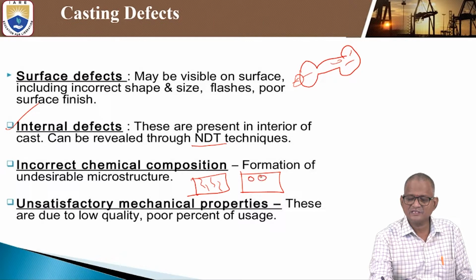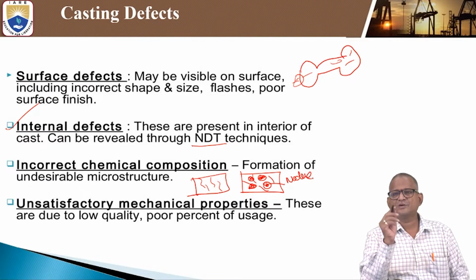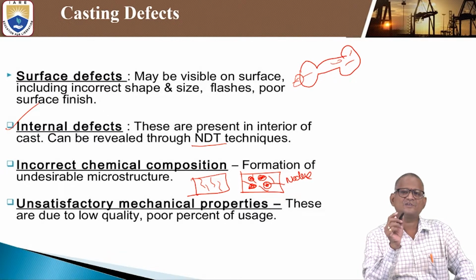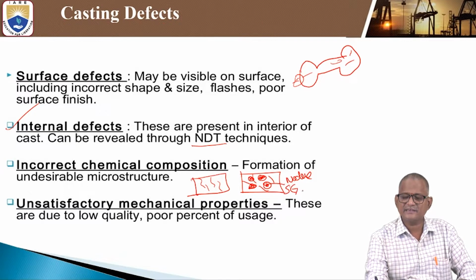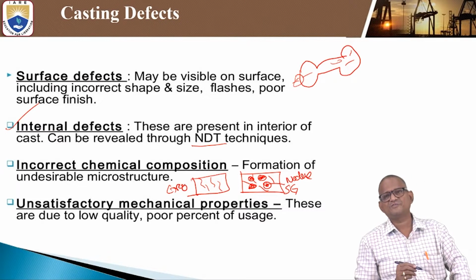In this microstructure, some nodules will form in the structure. This is called a nodule, like a small-diameter circle that will be formed. This is called SG iron, spheroid graphite. This is called grey cast iron. In grey cast iron, only flake-like forms occur.